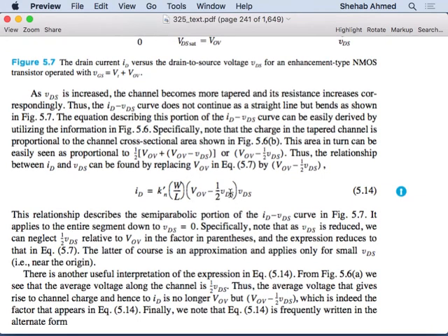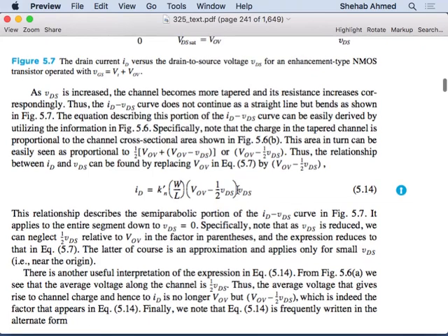How about the next step? I will keep VOV, but I will remove VDS and replace it with VOV, right? Because my VDS voltage is now VOV, and I will keep my VOV in the original. So it's Kn W over L, VOV times VOV, so it's VOV squared. So VDS equals VOV for that equation?